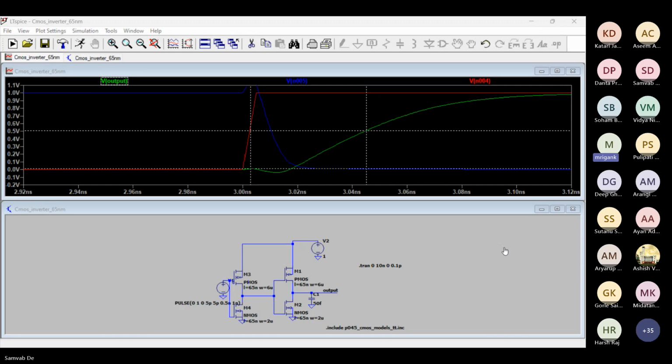Why will the power supply play a role in delay? You asked whether the power supply is going to play a role in delay. I said yes. What is the reason? Anybody? Very simple. The higher the power supply, the more charge needs to be deposited in the capacitor. So more current needs to be...